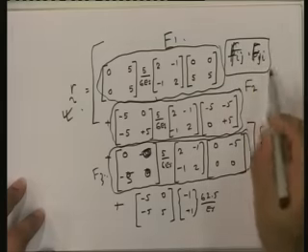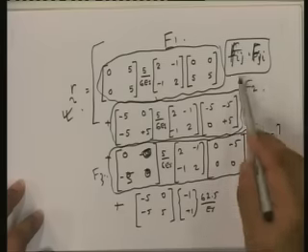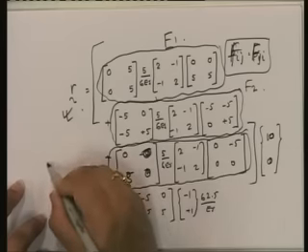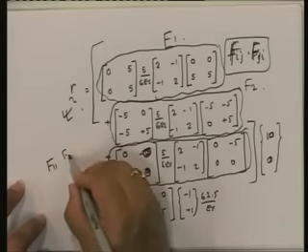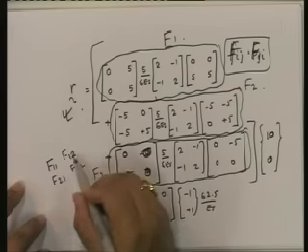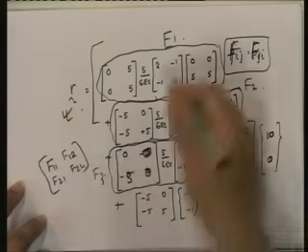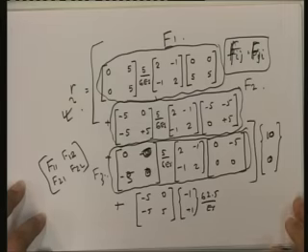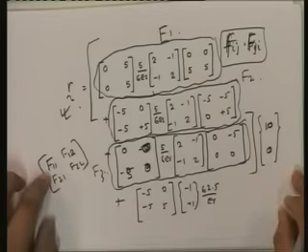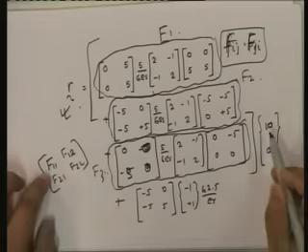Now, what is this flexibility? If you look at it, what is F11? You will get F11, F12, F21, F22. Okay, each one you can evaluate. What do these mean? Let's look at this. What does F11 mean? F11 is the displacement at 1 due to a unit R1, capital R1.